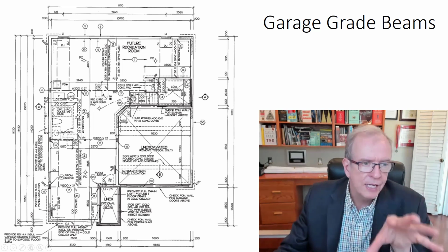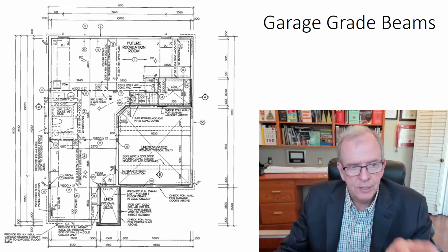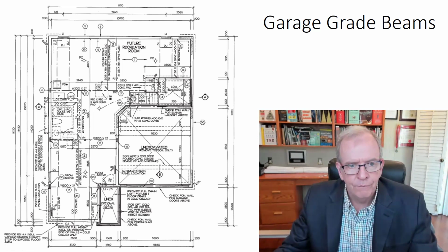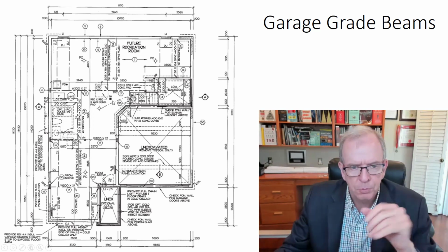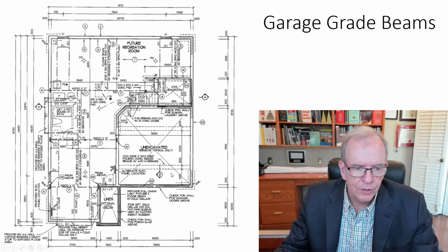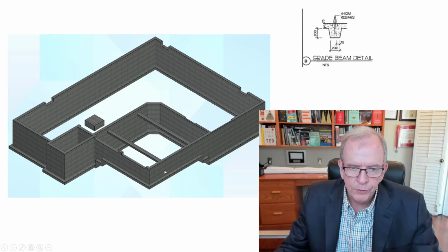What do I see on this plan, and what don't I see? That's the other thing, because you don't see depth, you don't see heights of information. That's where you've got to look at an elevation drawing. So every drawing has its purpose and the type of information that you can see. So that detail B, which is also on the drawings, is on the full drawings on the bottom left corner. It's a reference. Look for detail B.